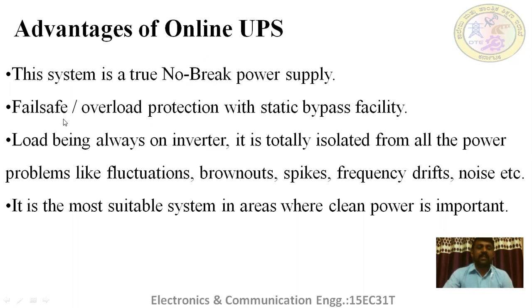The next is fail safe or overload protection with static bypass facilities. This is achieved by static switches, that is, the UPS consists of a number of static switches to avoid overloads and source failures. Also, the load being always on the inverter, it is totally isolated from all the power problems like fluctuations, brownouts, spikes, frequency drifts, noise and so on. Let me explain what these problems are.